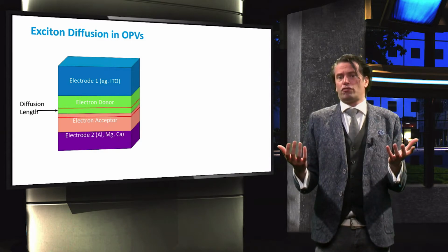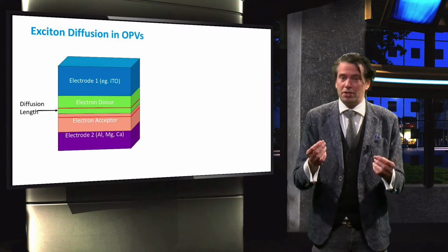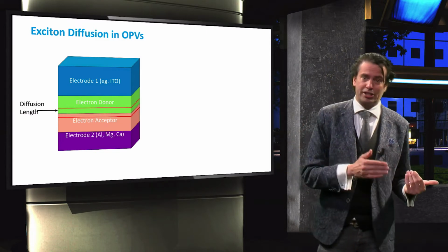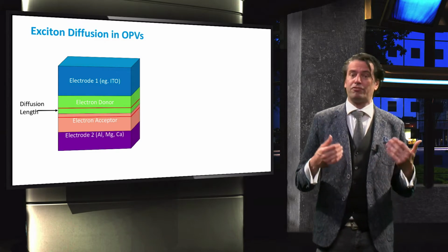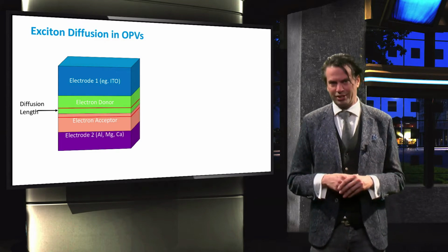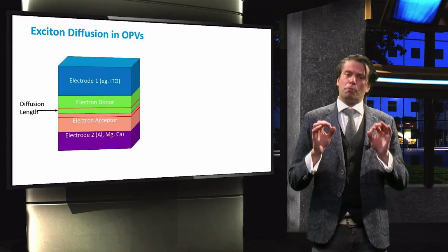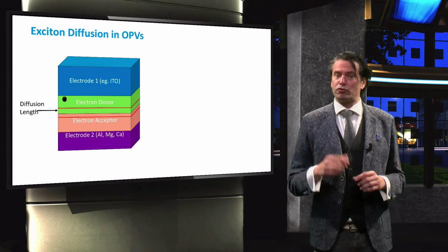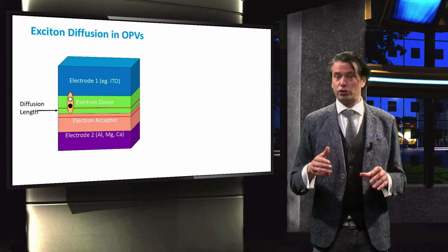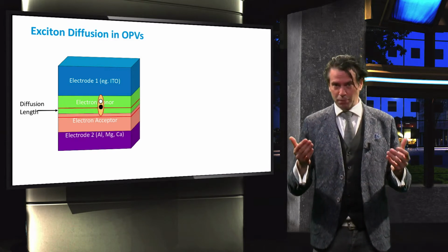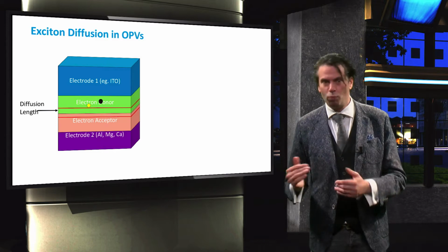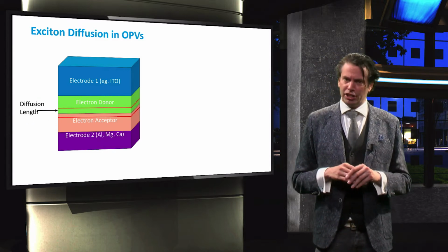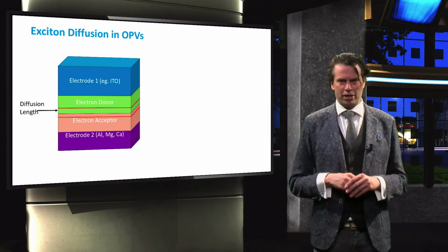The total thickness of a solar cell absorber layer is limited by its diffusion length, which in this case is much shorter than what is required for satisfactory absorption of incident light. The probability of absorption of light within a region of 20 nanometers from the heterojunction interface that leads to effective charge carrier separation is very low.